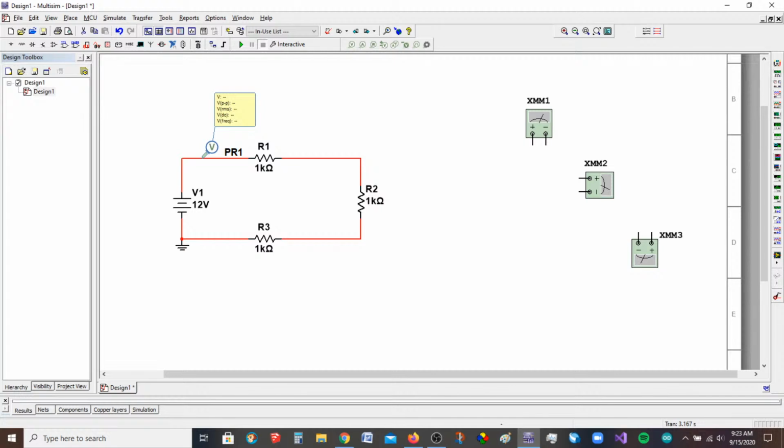So first thing I want to show you is the voltage magic probe. So if you just choose the 1 volt meter like this, what it's going to tell you is what the node voltage is. So the node voltage right here, right? The node voltage is always referenced to ground. So if you have your red lead here and you had your black lead on ground, or on another ground, what is that potential at this node compared to ground? You know, -0. I'm going to leave this right there because this thing should measure positive 12 volts because it's connected directly to this positive 12 volt terminal.